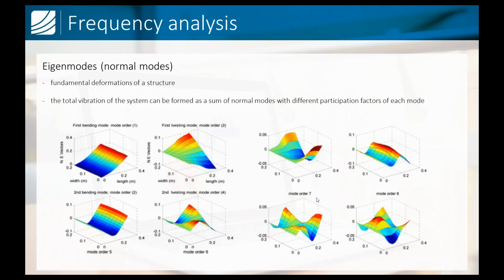And of course, what is interesting for us is at which frequencies we will have deformation and how it will look. At the same time, the frequency analysis has one weakness. It provides us only with the general shape, not the real deformation that would happen with a particular vibration exciting the system. So the result can be scaled arbitrarily, and it may look terrifying, but in the end, the real deformation is just a micron.